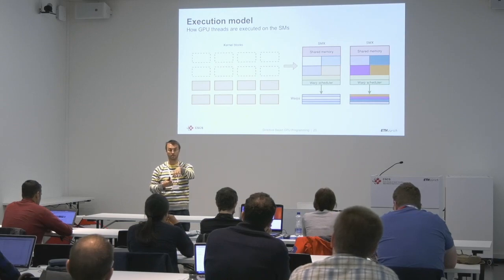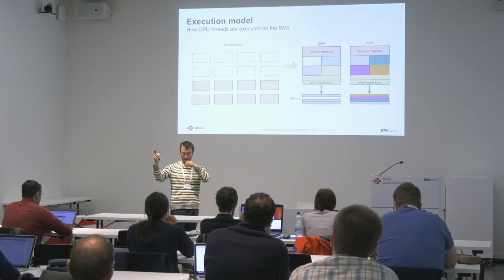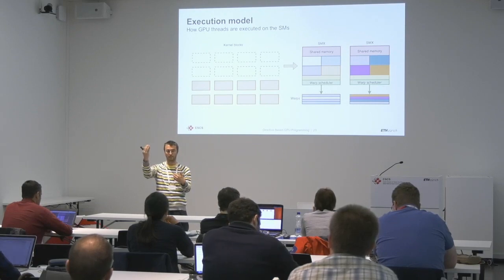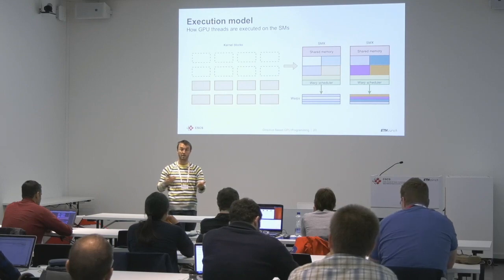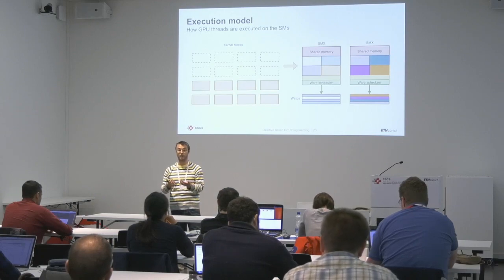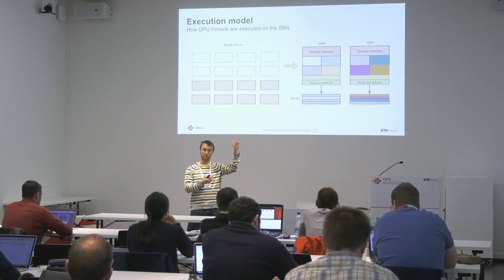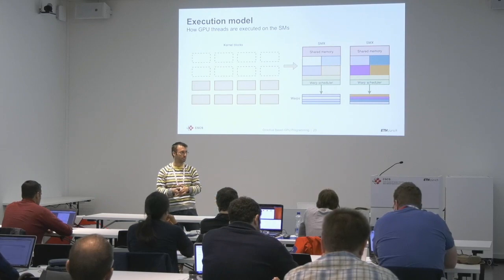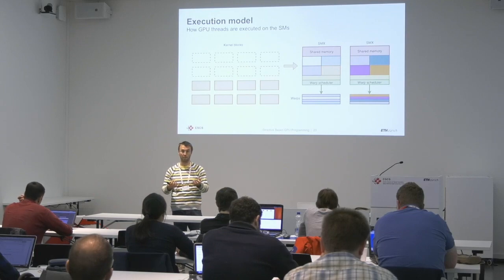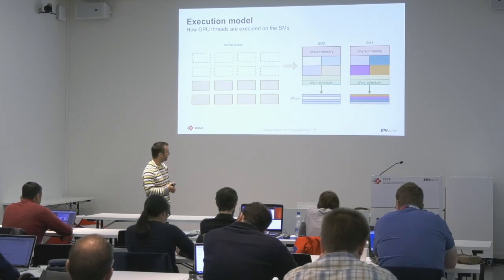So the register is where you actually have your current state of execution. Even on CPUs, all the operations you do work like this: you get data from the memory into registers, then you do your additions, multiplications, all your calculations there, and then you store your data back from the registers to the memory. So you can imagine the register file like the scratch pad of the processor, where it does all its operations. The same is true here.